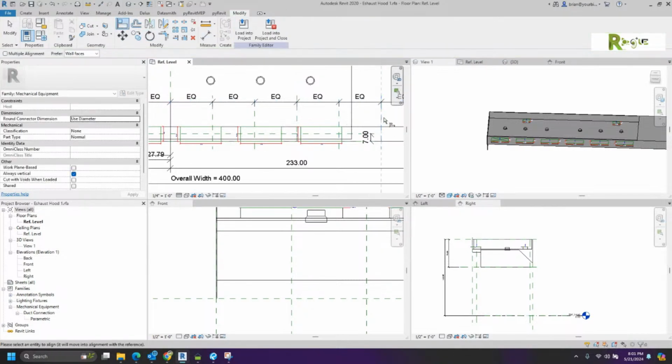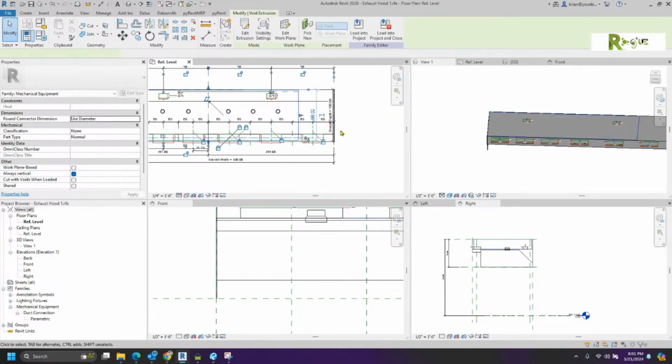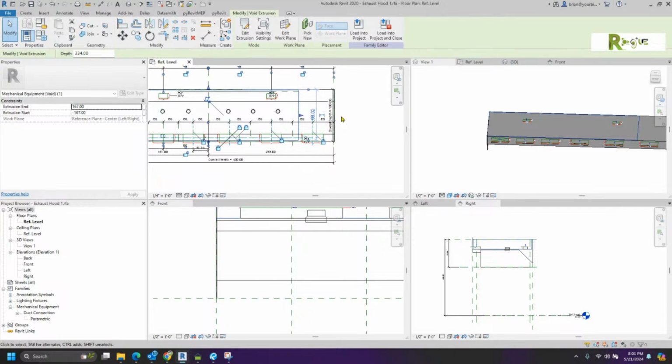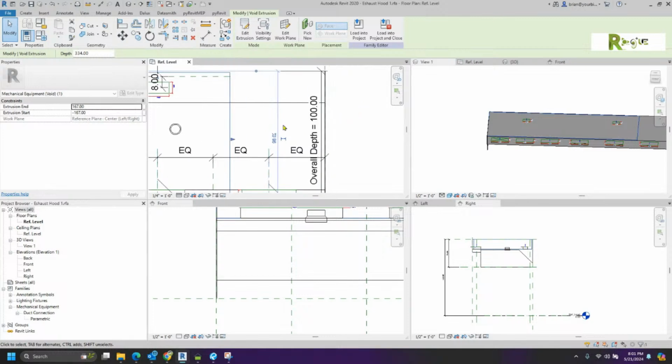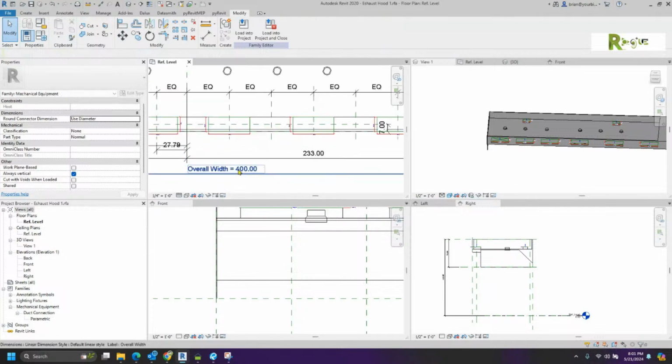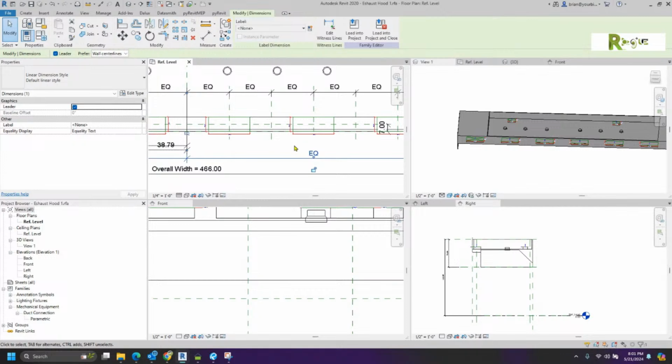Wait. Skip one. Skip one. You know what that guy is? That was my extrusion cut. And it's just because he wasn't locked down to the reference plane down there. And it's at both ends. This one here should say equal. And that centered everything up.